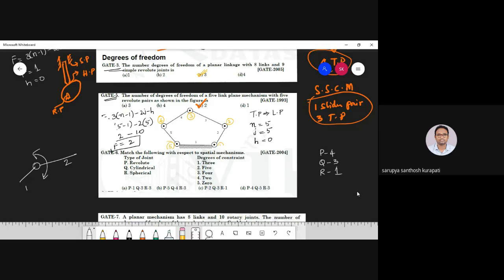Along the x-axis you can't have translation, along the y-axis and also along the z-axis you don't have. So these are not possible. So how many restrictions in 3D? You have 5 restrictions. So that means P goes to 2. Option C. That's it, right? Yes, sir.